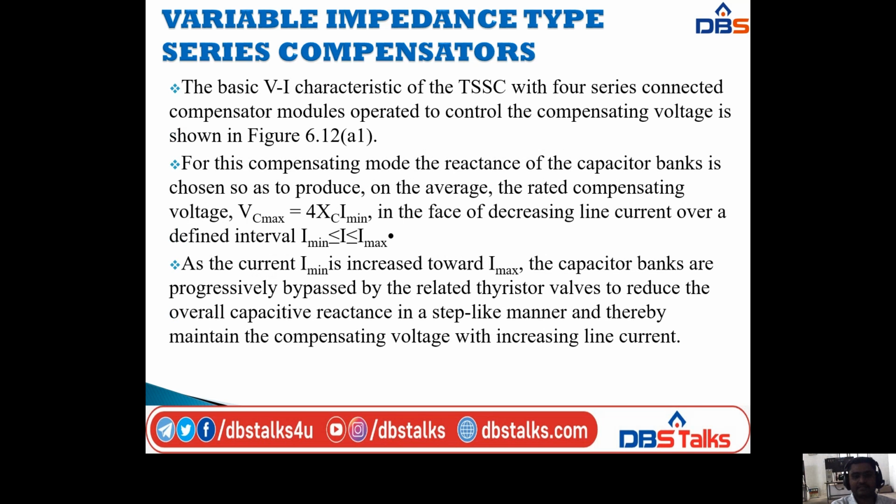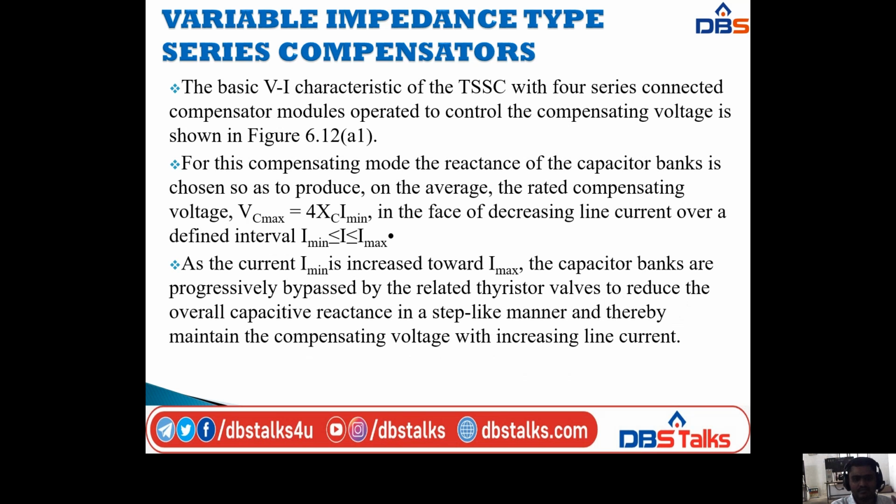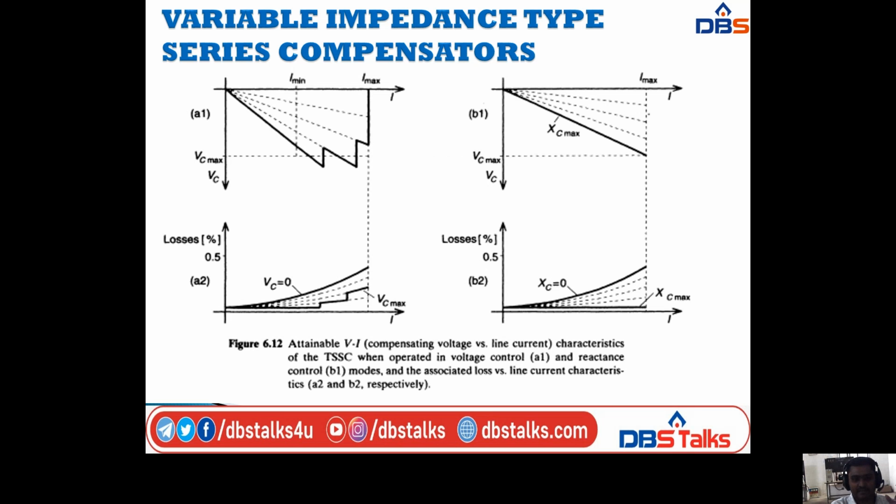The basic VA characteristic of the TSSC with 4 series connected compensator modules operated to control the compensating voltage is shown in this diagram. The first diagram, A1, gives the VA characteristics of the TSSC when operated in voltage control. In this compensating mode, the reactance of the capacitor banks is chosen so as to produce on average the rated compensating voltage, that is, Vc maximum is equal to 4 times Xc times I minimum.